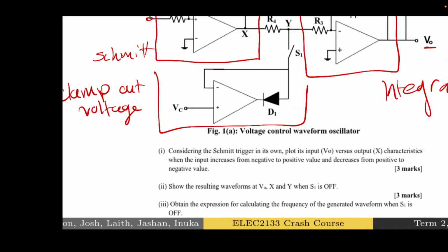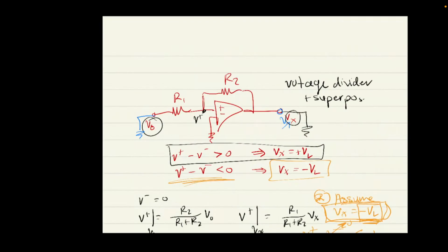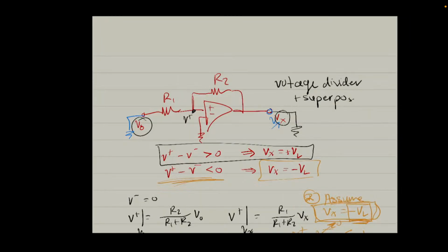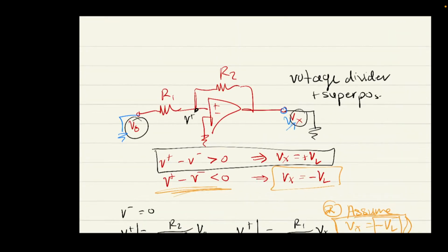Okay. How do we do that? Okay, the first thing to notice is that frequency. So we know we can find the period using RC charging, which we'll get to in a second. But the thing I want you to keep in mind is that the frequency is 1 on T. So we can just find the period and then take the reciprocal, and we've answered the question.